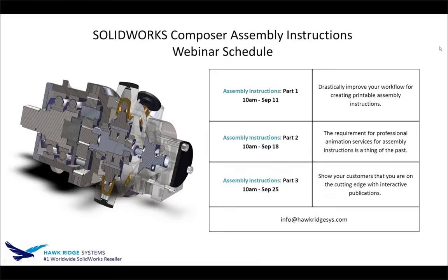So, if you're using, let's say, Microsoft Word, and you're taking all the imagery out of here, and we're linking that into Word, not embedding it, but linking it, then when it updates in SOLIDWORKS, it updates in Composer, it actually will update in the Word document, and that will all be lined up with the individual images with the pages associated with the document. So there are ways to do it. The way that I showed it today, there's no automated way to do that, but there are definitely ways to get around that.